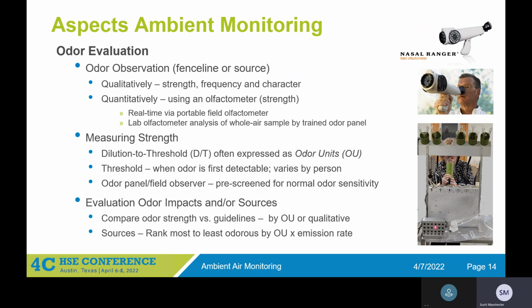But those are qualitative. Odors can be evaluated, especially for strength, quantitatively, using olfactometers, and those essentially are devices that the odor goes through, and then clear odor-free air is mixed in and dilutes it, and by how much tells the strength of the odor. There are versions of real-time olfactometers that can be taken out in the field. The one on the upper right is an example of a real-time field olfactometer that can be breathed through, and then the mixing of odorized air with clear fresh air and the dilutions are changed.